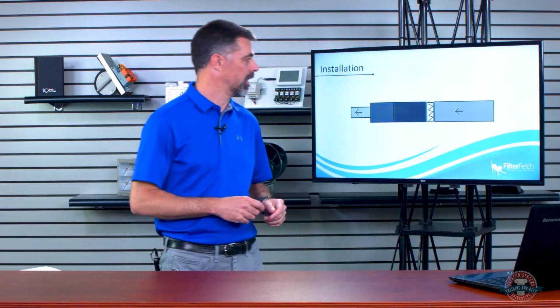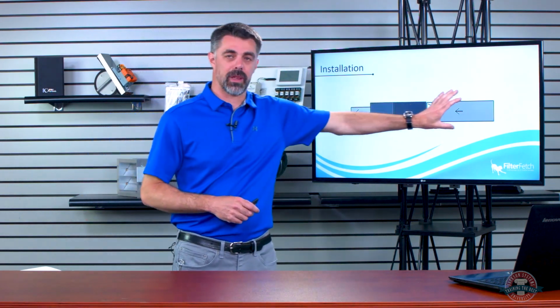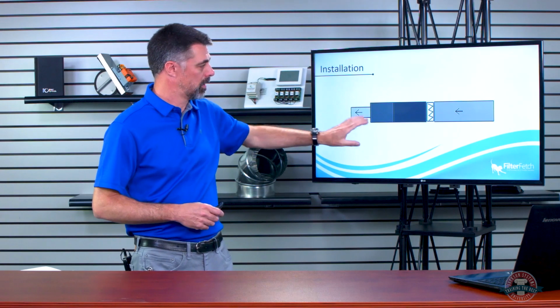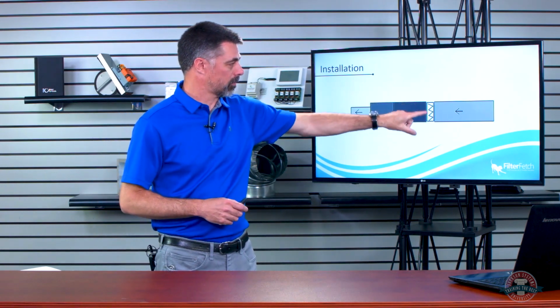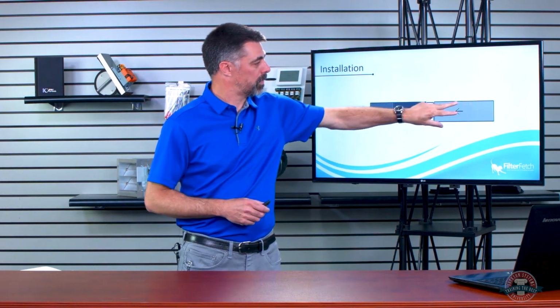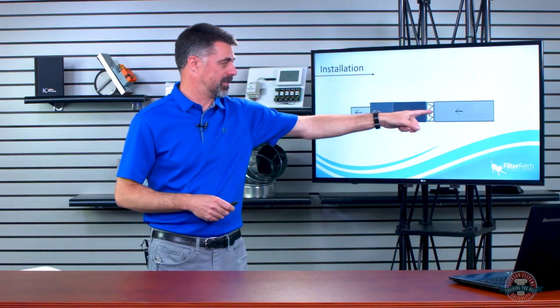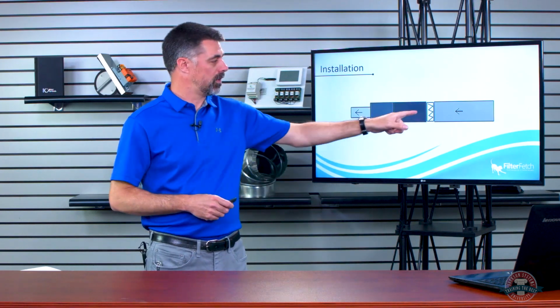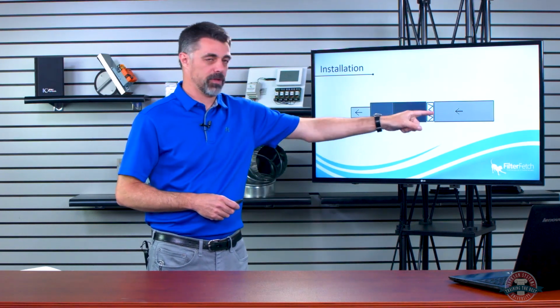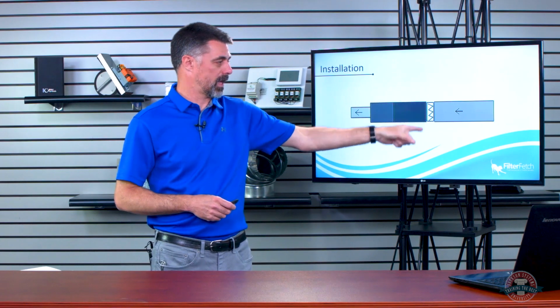Now, let's get into talking about different system types. Okay, this is what we see a lot in a horizontal system. Size that filter rack right for the same size as the equipment. Sometimes that duct is even pinched down smaller and will expand as it comes into the filter rack. This is a place where I'm going to make sure I test that because I want to know what the drop is across that because I'm going to look at that filter.